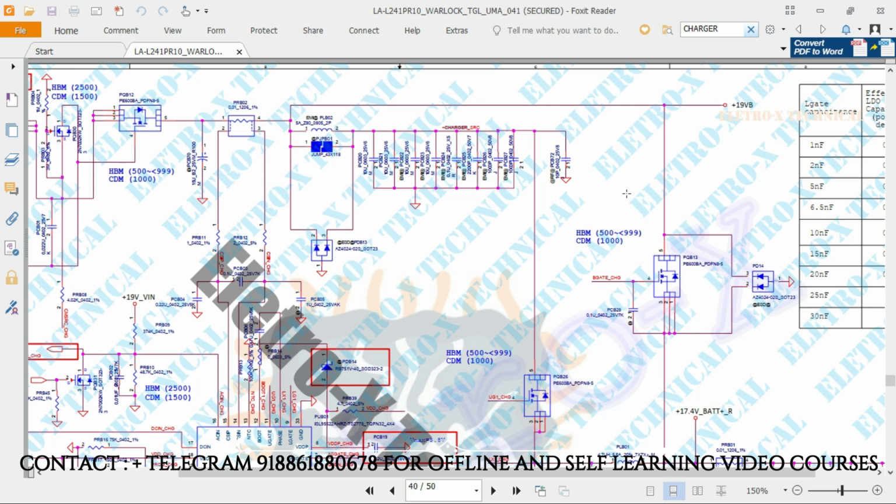This is the second condition after the V-in circuit. First, 19 volts V-in goes to the charger and first MOSFET. If the first and second MOSFET voltages are good, then we get the 19 volts VB that will activate the high-low MOSFET sections, the high MOSFET drains. And in this particular 11th generation board, individual ICs are used for 5 volts and 3 volts.